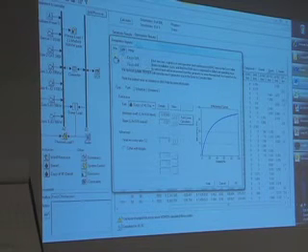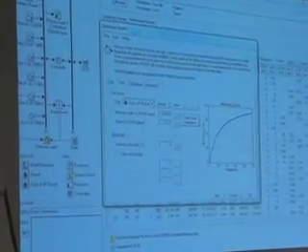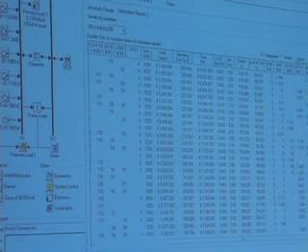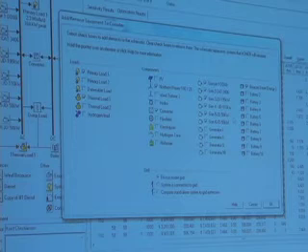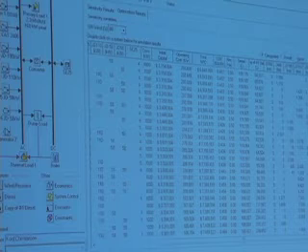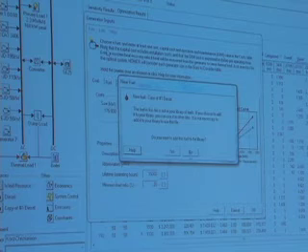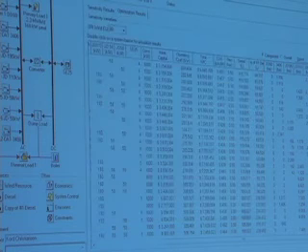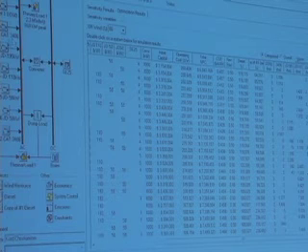So I can come in here and go Edit, Copy XML, and close it. And then I can come here and I want to put in another generator with exactly the same characteristics. So I added a generator. I come in here and go Edit, Paste XML, and now I've got an exact duplicate of that generator here. The CAT 3406, generator 2, CAT 3406.